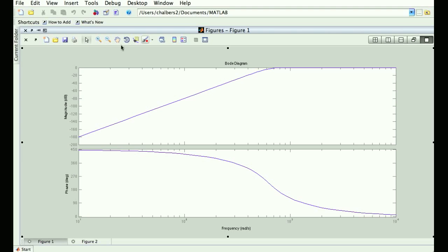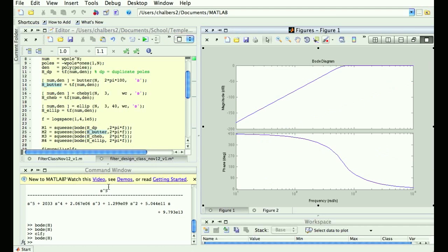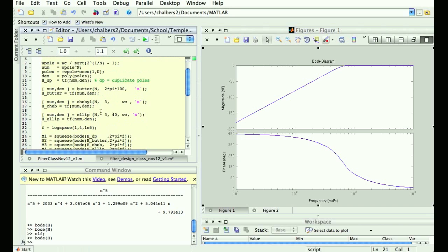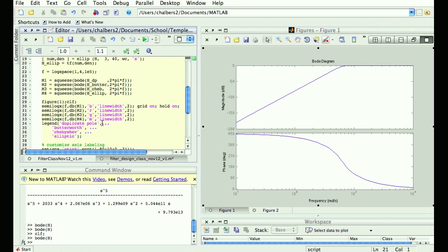But I definitely wanted to get this out here for today. I want you to download this code and look at it. You've got examples. This is building the Chebyshev filter, the elliptic filter. You should experiment with high-pass filters, stop-band filters, because those will be basically the tools that you want for your computer assignment. I don't think I put this in the computer assignment, but I would like everybody to use the lsim command to simulate their filters. There are other ways of doing them, but those are digital filters, and sometimes those lines get blurred a little bit. I want everyone to stick with the analog filtering techniques, okay?